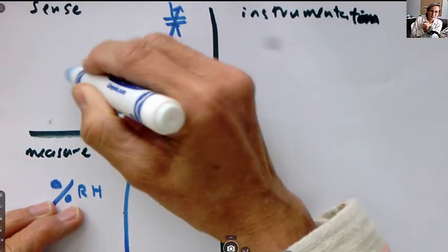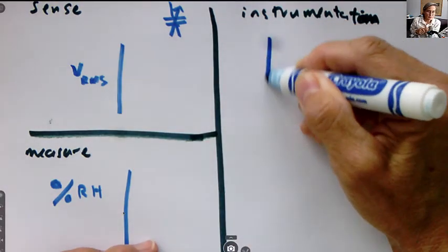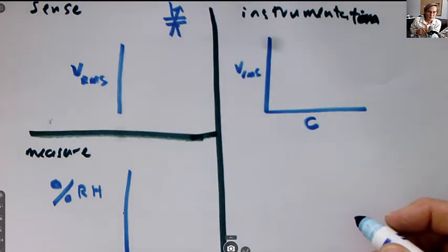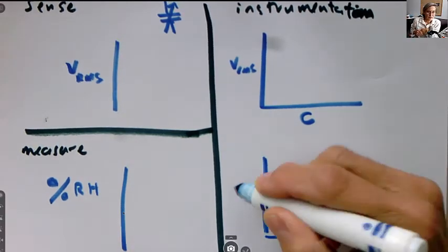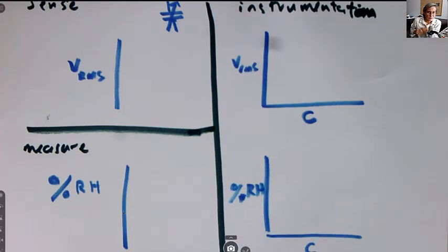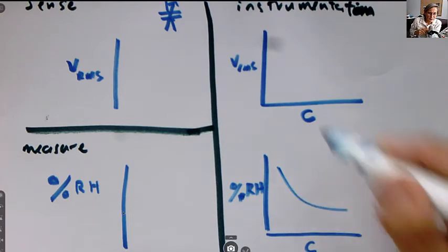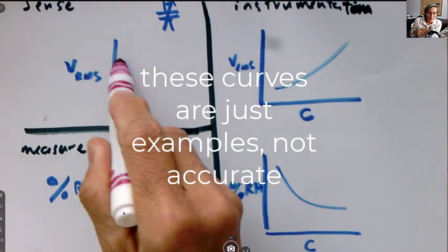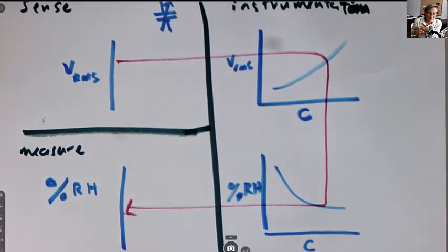Okay, let us put it all together. We're going to take a RMS voltage measurement that is from that sawtooth wave, and the instrumentation is basically giving us that RMS value with respect to capacitance. So as the time constant changes with capacitance, we'll get a different value. The sensor comes with a transfer function that relates relative humidity to capacitance, and we're going to go from the voltage measured to this relative humidity, and I'm just drawing some curves here just to show you an example. So we want to measure a sense of voltage and then let that get us to the relative humidity value.